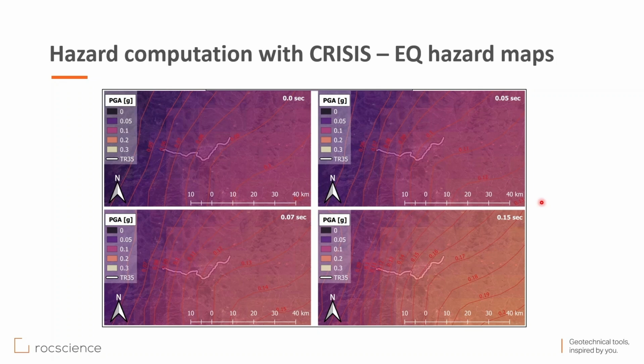As a result of the study carried out in the framework of this project, the bedrock peak ground acceleration and the response spectrum were calculated for the entire Cluj-Napoca area, and summarized in a map appendix, with maps prepared by using QGIS. We selected the response time periods required for the construction of the design spectrum for future design work in accordance with the requirements of both Eurocode 8 and the Romanian regulations. These are the following response time periods: 0, 0.05, 0.07, 0.15, 0.4, 0.7, 2, and 3 seconds. The following return periods were used: 95, 225, and 475 years.